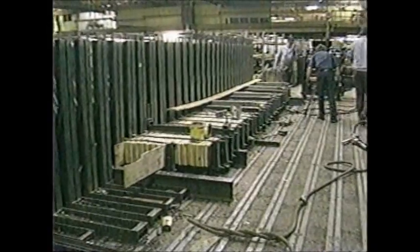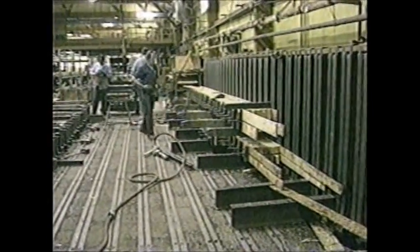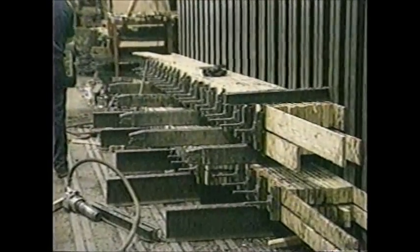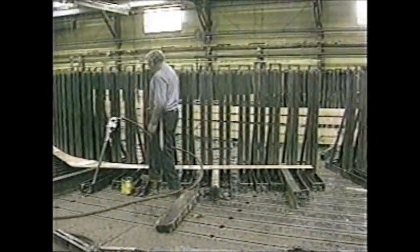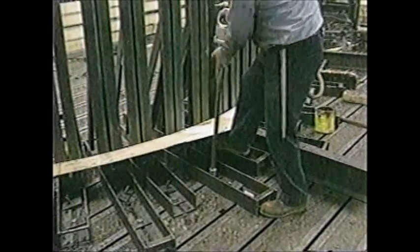The beam we have seen assembled and clamped is a straight beam, but complex shapes and arches are routinely produced. We'll see some of these further into the production line. This jig is being assembled by bolting jig elements to the special grooves or slots in the floor, following the pattern for the arch, which will be laminated in the jig.